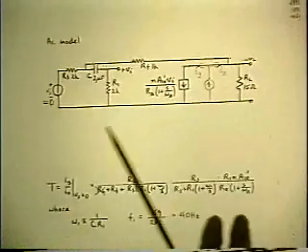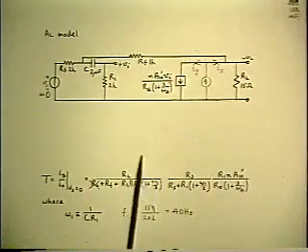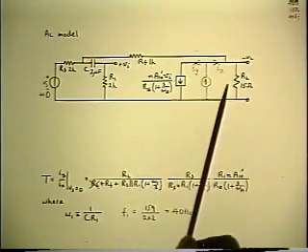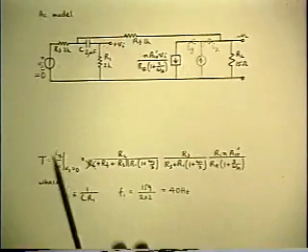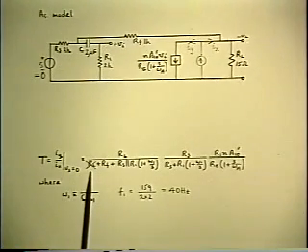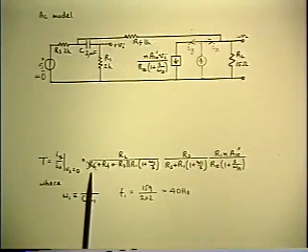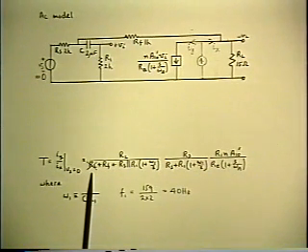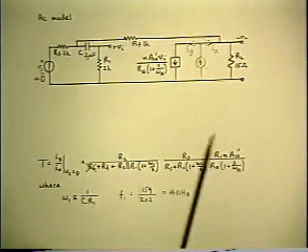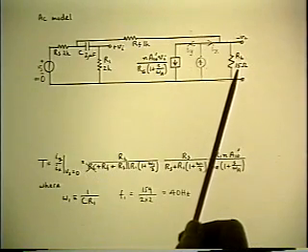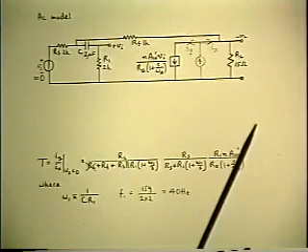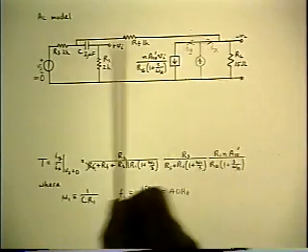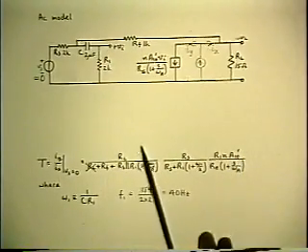And here it is. The very first line when we wrote down the loop gain by injection of the IZ. There it is. Dropped the RL. For the very good reason that RL is 15 ohms compared to RF, which is 1K. And I mentioned at the time, that's a very good approximation.